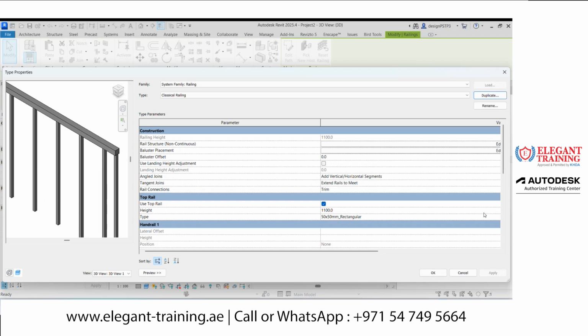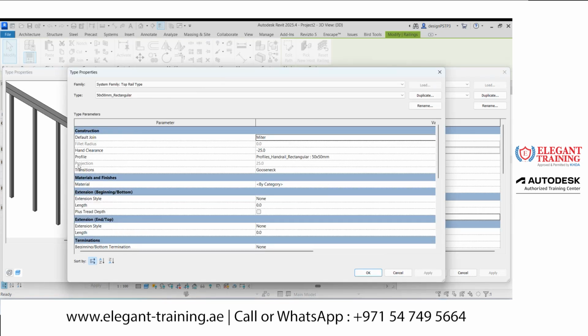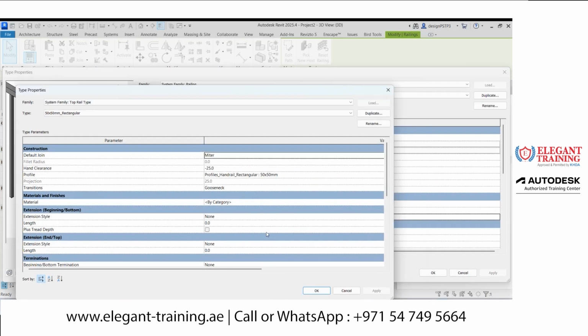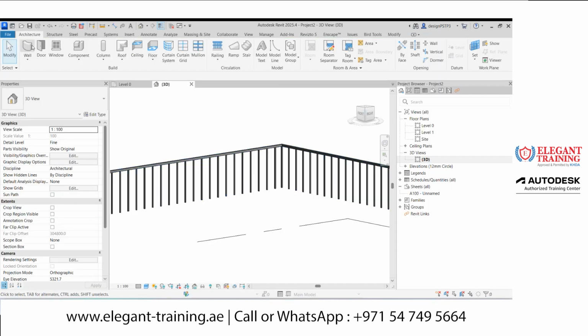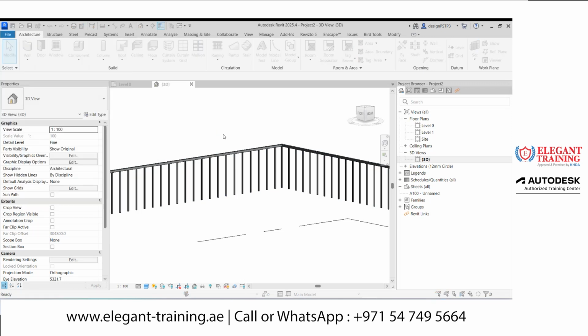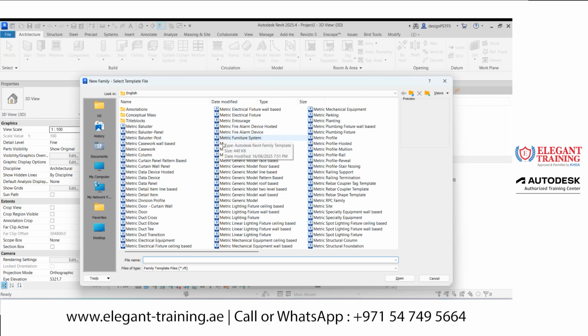And this is the type. If I'm editing the type here, you can edit more things for the top rail over this side. So I will create a profile and load it here. From this project itself, I can go to File, New, Family. When you are creating a family, you need to choose the right template, then only you can load it in the exact place. For the top rail, in this English folder, if I go to the profile side, I choose the Profile Rail and click Open.